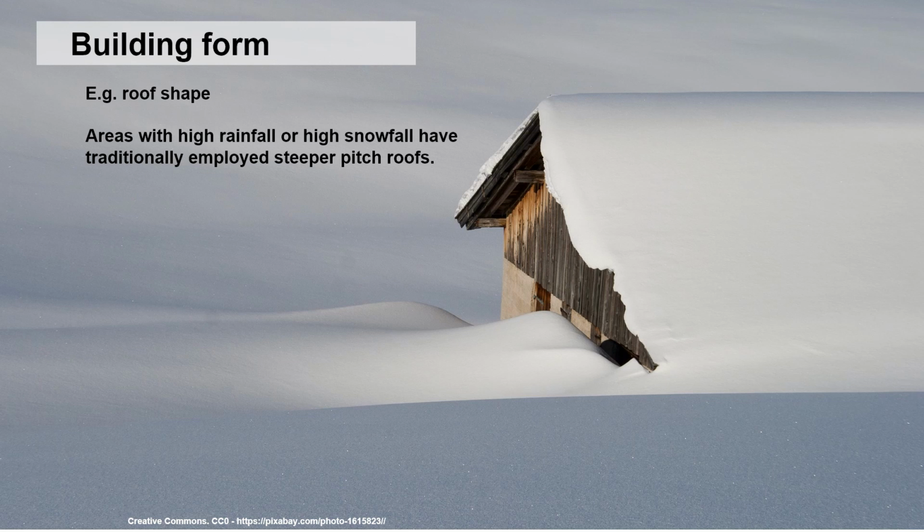The longer water sits on the roof, the more chance it's going to be able to find a path into the building. So to evacuate the water quickly, we would build a pitched roof to be able to push that water away from the building, and it would drop clear of the building. In Middle Eastern countries and warmer countries, they tend to have flat roofs. They're not really concerned with the amount of water sitting on the roof because they tend to get that in a deluge. They wouldn't necessarily have it over an extended period of time.